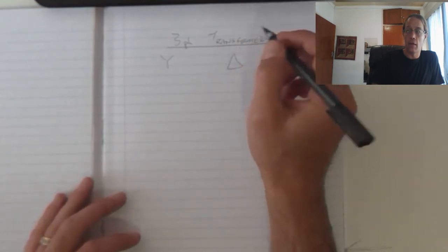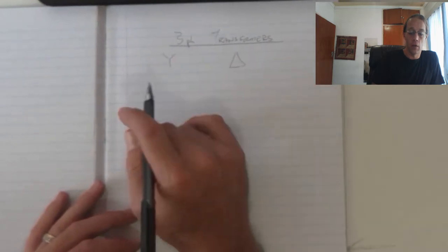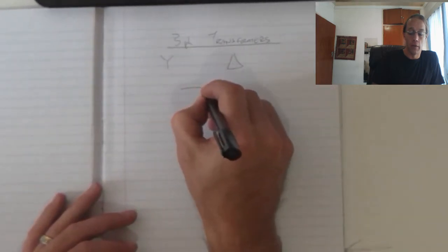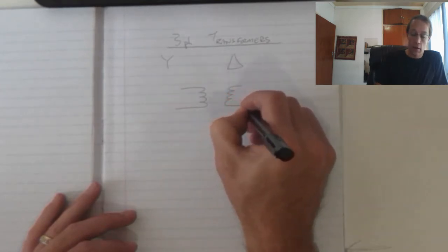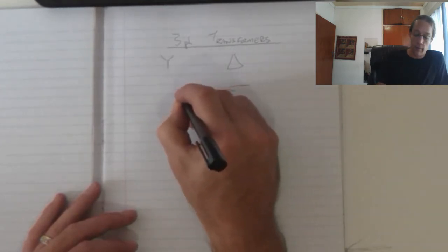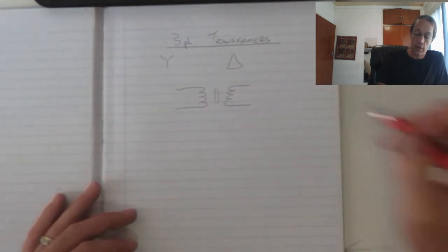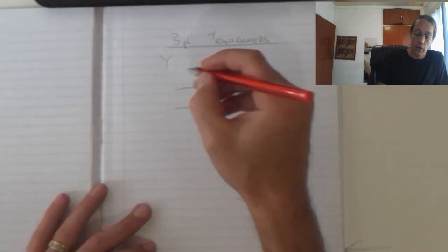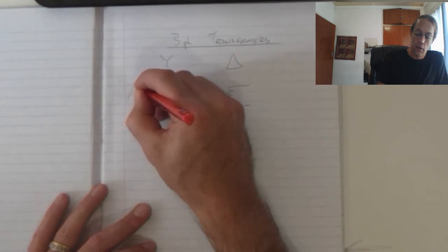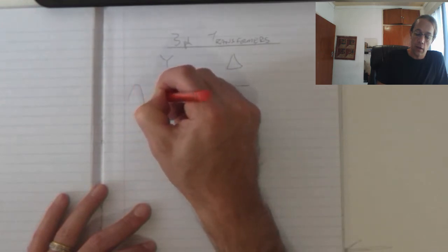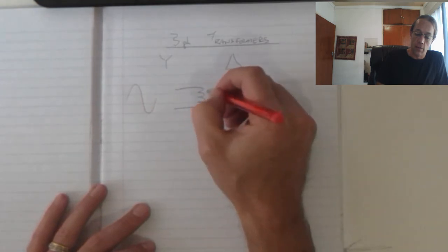Now when we look at the actual three-phase transformer, ignore the three phases for a second. We're just going to look at a single phase, and we can see that we've got one coil that is magnetically connected to a second coil. Let's call this our red phase. Now with our red phase, as we supply our voltage on the input, this will allow a current to flow through my primary coils.